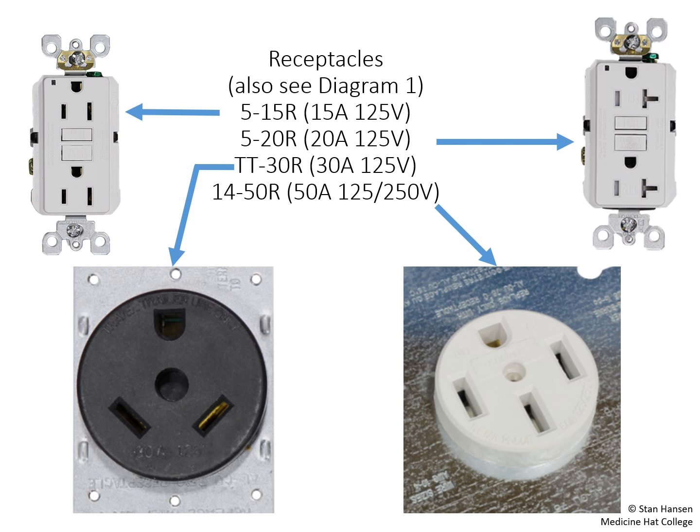Depending on the size of the unit being parked on the site, we could use any one of these 4 items. For example, very large motorhomes would use the 14-50R, whereas smaller units that incorporate an air conditioner will usually use the 30 amp receptacle. Any trailer that does not have an air conditioning unit can use a 15 or 20 amp receptacle, or if we're looking at tent sites, that would also incorporate those 2 types of receptacles.